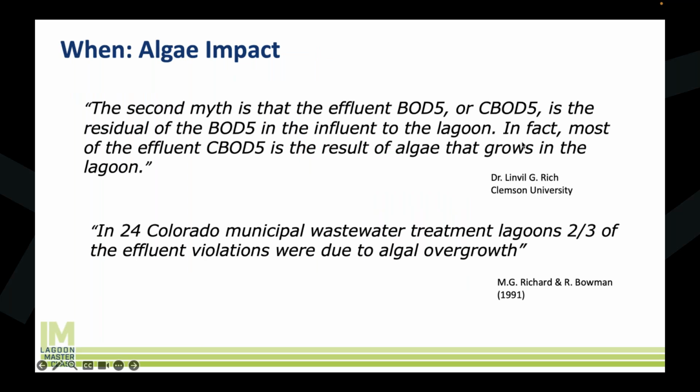And then the when also is very important when it comes to algae itself. So Dr. Linville Rich, one of the sort of godfathers of lagoon study, passed away some years ago, wrote several books on lagoon treatment, really kind of an authority on this stuff. If you are interested in having a textbook on lagoons, he's got some good ones. And he said, the second myth is that the effluent BOD5 or CBOD5 is the residual of what's coming into the influent lagoon, when in fact, most of the effluent BOD5 coming from lagoons is due to algae growth.